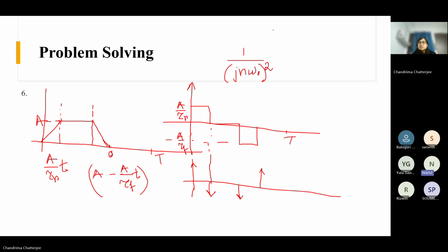First of all, let me just say this: whatever switching frequency, if it is a high frequency PWM, you will obviously have to do pulse width modulation, right? Whatever topology you are using, EMI EMC will come. There is no particular switching frequency you can choose for which your product will go through at any stage.